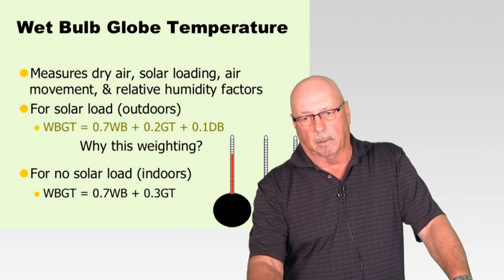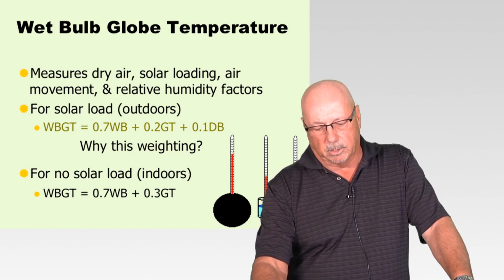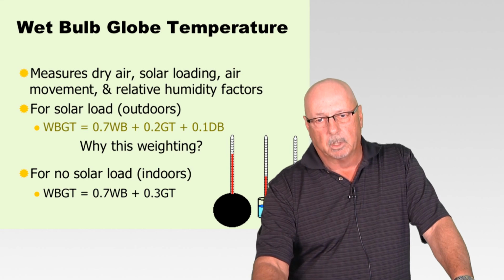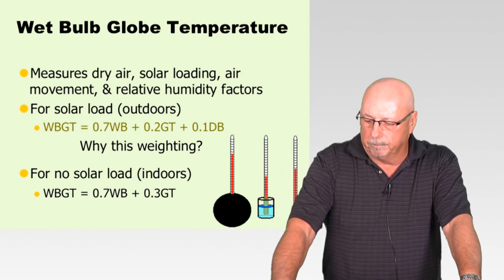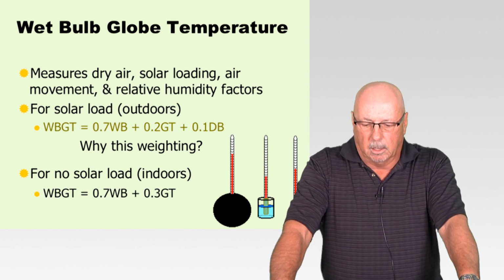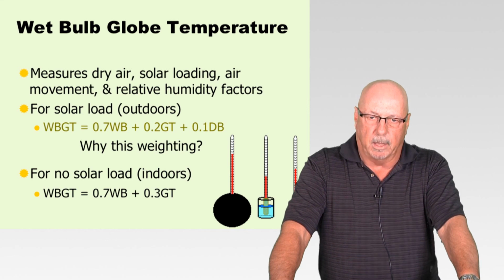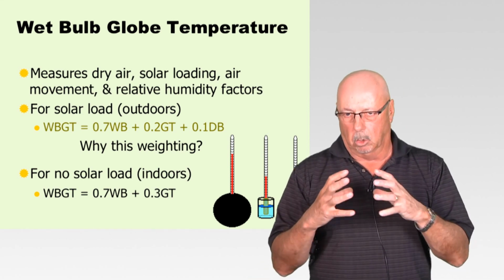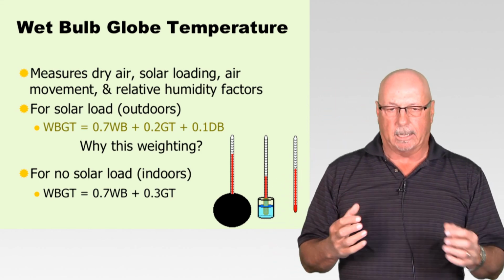And on their slide here, we can see on the far right, just a regular thermometer. That's going to measure our ambient temperature of what it is outdoors. The thermometer on the left, you can see that the bulb of that thermometer is submerged inside of a black globe. It's just a small little hollow ball, and it's painted black.